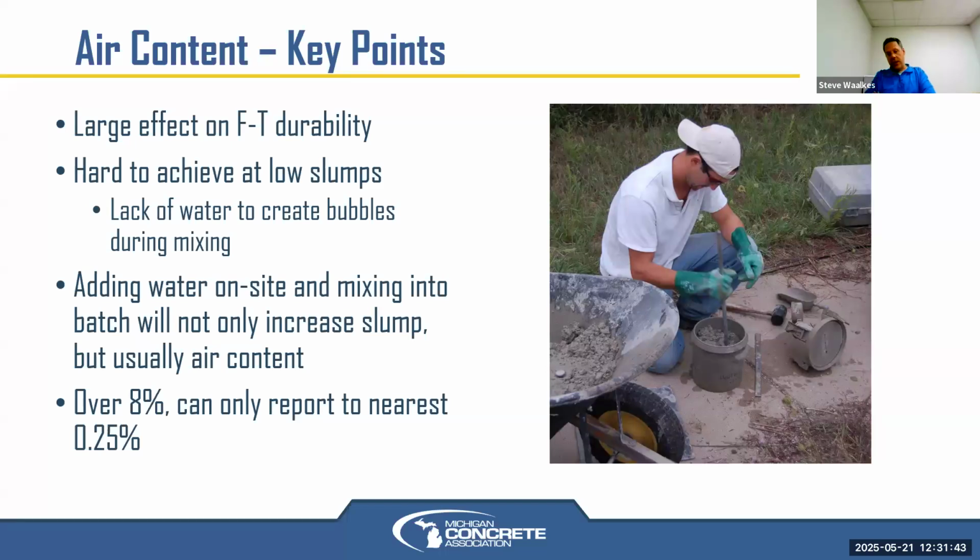There are air detrainers that will pop the bubbles. It's like bacon grease left in the pan: it doesn't create a lot of bubbles when you try to scrub it with soap and water. Bacon grease is a detrainer in your kitchen sink, or any grease for that matter. It's not a grease that we're putting in, but there are chemicals that exist, though not every specification allows it.